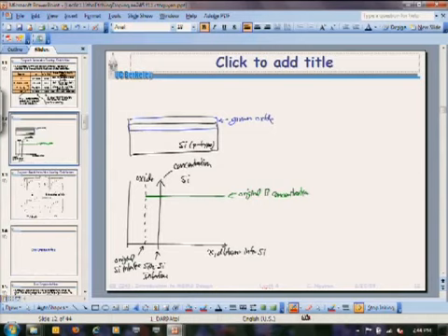Boron concentration. Deep into the silicon, it's still the same concentration as before, but up near the surface, you notice how it's been depleted. And then on top of this, once it gets in the oxide, it can't go anywhere. So this boron is now all stuck in the oxide. There was no oxide before, but the oxide you grew now has a very large boron concentration in it.